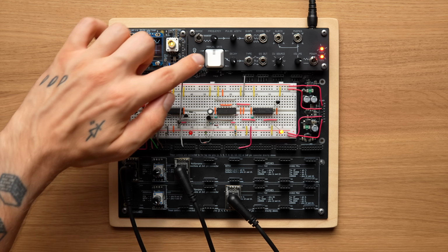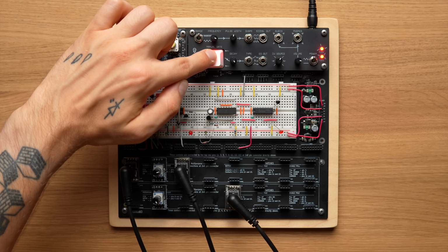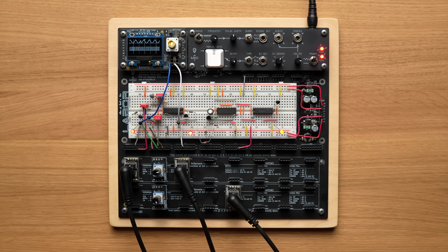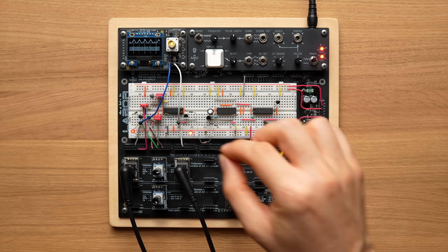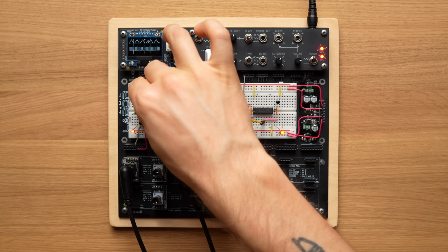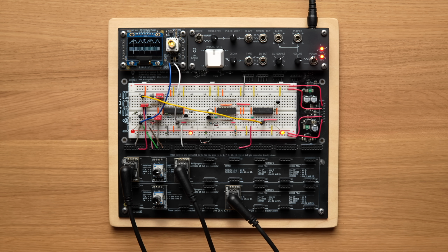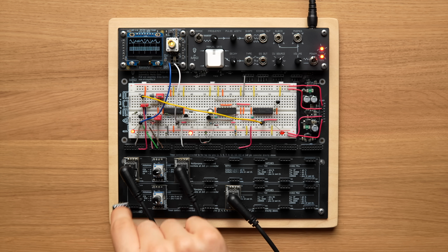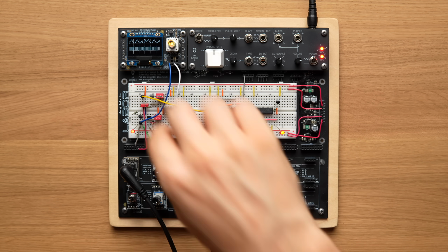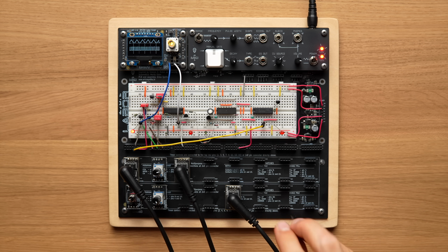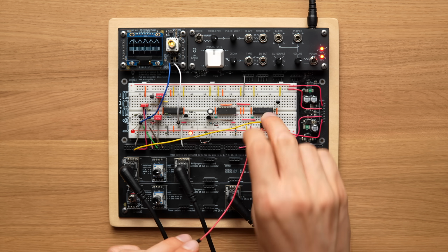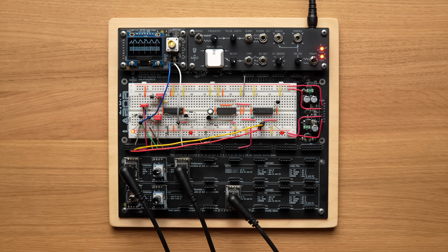Here's the original free-running version again, without sync. And here's what happens if I connect the 4520's half-note output to the new LFO reset input. We can even take this a step further. I'll set up a 3-way switch so we can either let the LFO run freely, sync it to the full pattern length, or sync it to half the pattern length for even straighter accents.